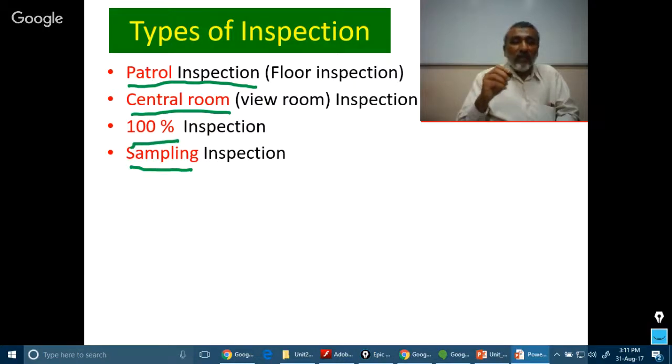Also, we need to remember that sometimes we go for the destructive test. In a destructive test, 100% inspection means 100% destruction. There we can only go for sampling inspection. We can only take a sample of the total products and inspect that. For example, if you take chocolates, if I had to go for 100% inspection of the chocolates, I would have to eat all the chocolates. There would be nothing left for selling. So many times it is not possible to go for 100% inspection. Sampling is the only option, but the experience says that many times sampling gives better result than the 100% inspection.